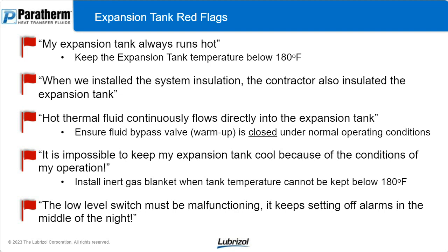You want the tank to run cool. You want any radiant heat that gets into the tank to dissipate. Insulation will prevent that from happening. Remove expansion tank insulation at once. Another red flag: hot thermal fluid continuously flows directly into the expansion tank. Now, some designs have this with a thermal buffer tank. That's a little different. If you have a bypass valve or a warm-up valve or some kind of boil-out valve that is open during normal operation, that's going to continually put very hot thermal fluid into that tank. That's going to cause a lot of oxidation very rapidly. You want to make sure that that bypass valve is closed under normal operating conditions.